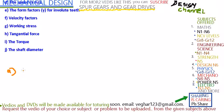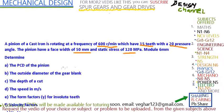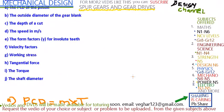Pitch circle diameter, which is the diameter of a gear. So the equation of PCD is this: M represents the module, then the teeth. Multiplying this together will give you the PCD. So what is our module? The module is 6 millimeters.